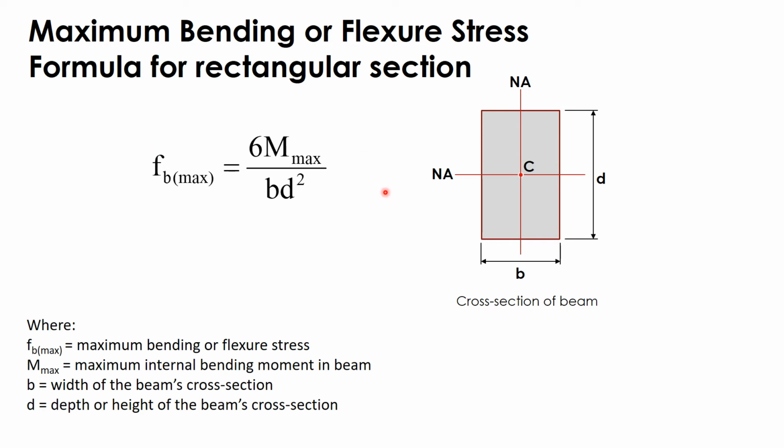But again, this is for rectangular sections only, and solid ones, because you may encounter a rectangular cross-section with a hollow portion. That needs a different or additional analysis. The maximum shear and bending stresses we derived are for a solid rectangular section.